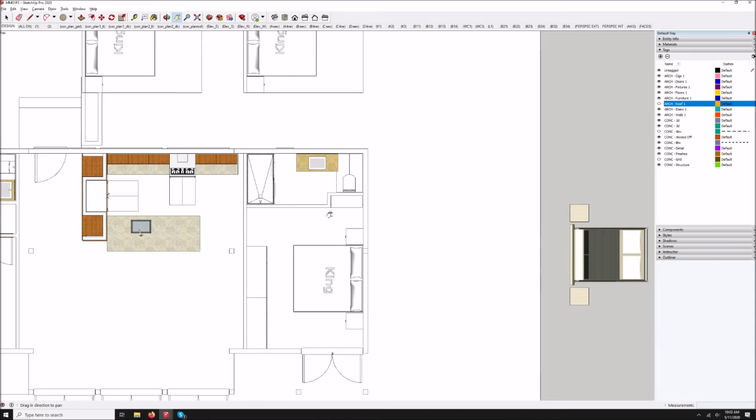I have the bathroom all lined up against one side. I made a little notch here because I need less depth for the toilet. In this case, I've used a toilet with a concealed tank that goes inside the wall. Because it's an interior wall, I can tuck the tank into the wall. I would not use that type of wall hung toilet against an exterior wall because I don't like to have the toilet tank in the exterior wall, which would significantly reduce the amount of insulation in that area.